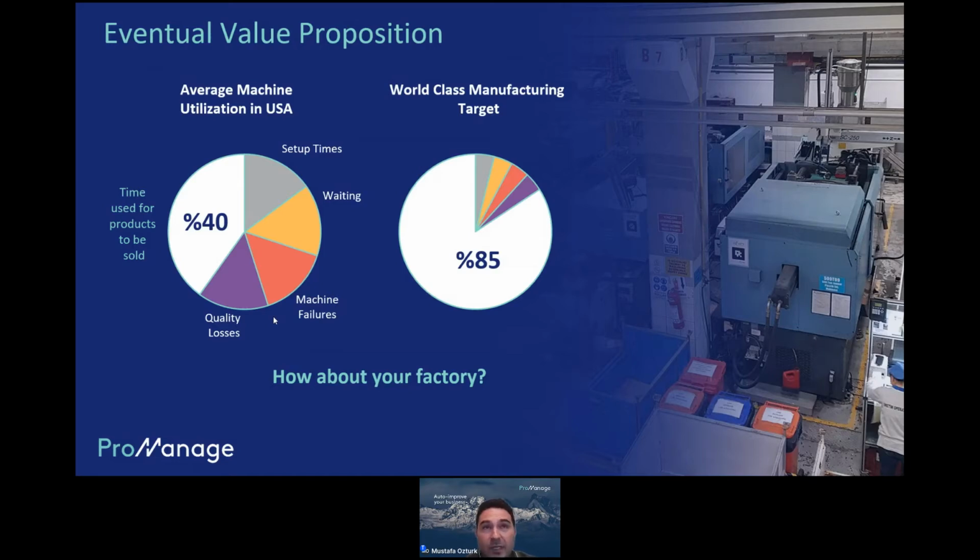You have a work order, you have a product, and since you know the cycle times and the raw material required for each cycle, you can estimate exactly when each machine needs to be replenished with raw material. Say you have 50 machines or 20 machines, you can estimate exactly when a machine needs raw material. And you can put it on a large TV screen in front of the person responsible for raw materials, and he'll know exactly which machine to attend to in order to replenish the raw material.